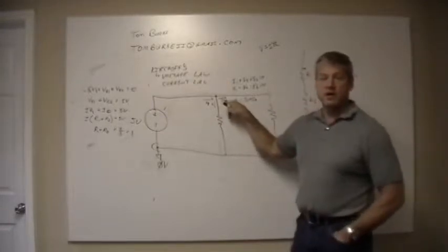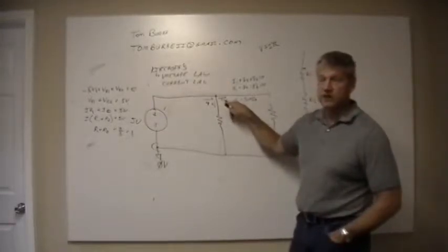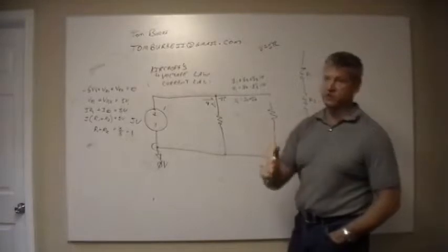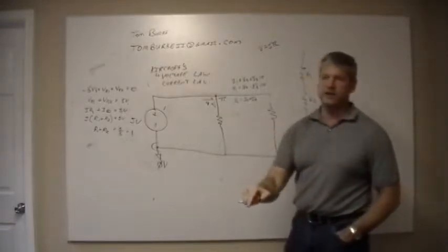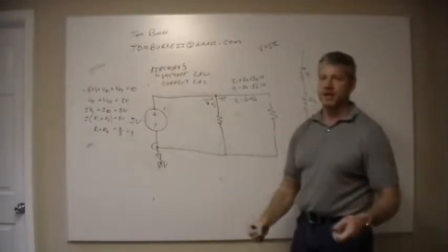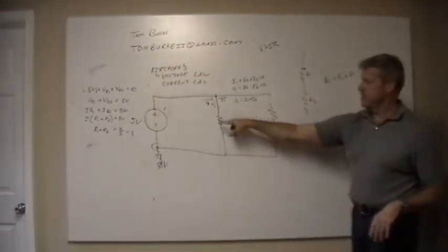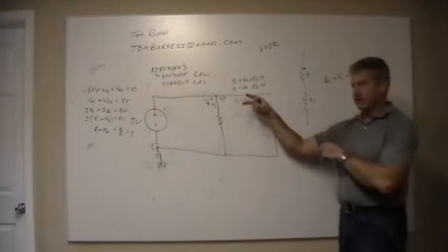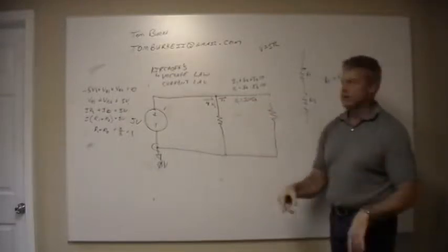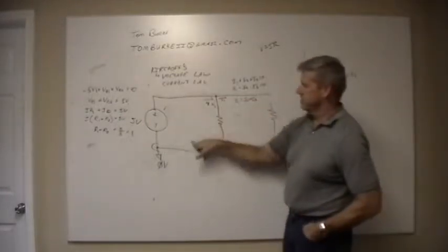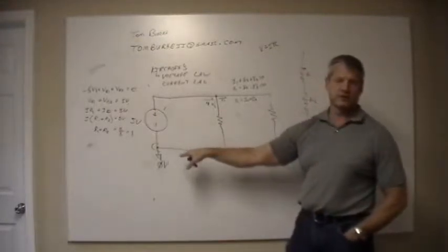This comes from the laws of thermodynamics. Energy can be neither created nor destroyed. I'm pushing current in, it's got to come out. And I can't create energy. It can change forms. I can make heat here by turning voltage and current into power. Basically here the current stays the same, but I lose voltage as I go across it.